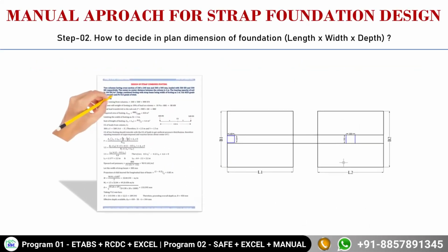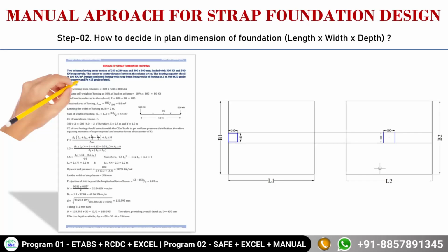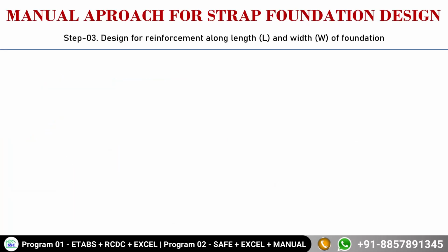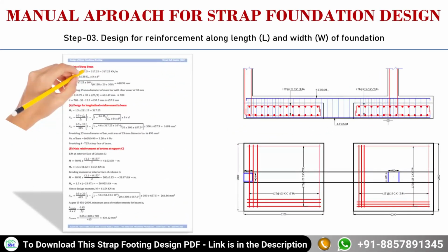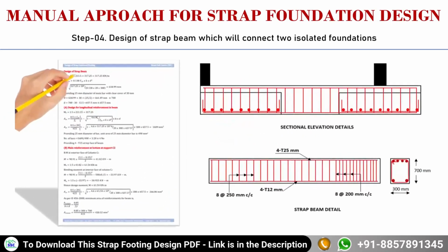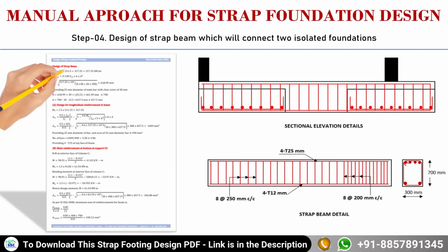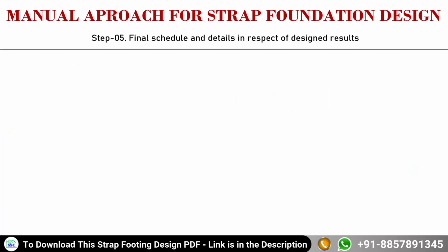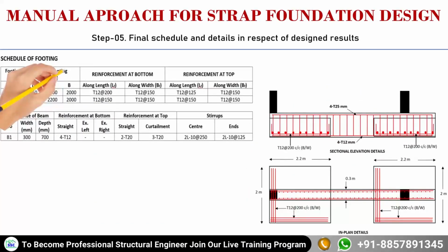In the second step we will see how to decide the plan dimensions of the foundation as length, width and depth. In the third step we will see the design for the reinforcement along the length and width of your foundation. And in the fourth step we will see the final design of your strap beam which will connect two isolated foundations. And in the last step we will see the final schedule and detail in respect of your design results.